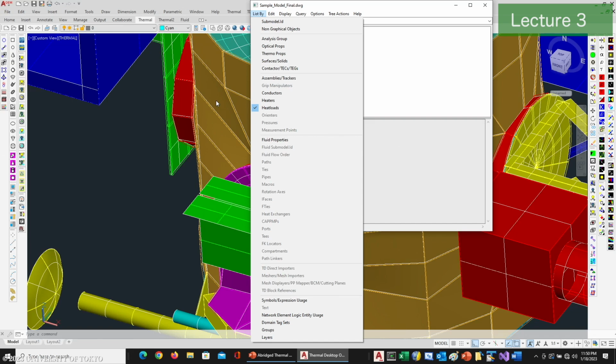So now there's no longer a need to line up my nodes with where my thermocouples are for testing. I can just put a measure there, and it will do the calculations to figure out what that temperature needs to be there. It's basically using the same algorithm that is used for the mapping of structural grid points onto thermal surfaces. Using those shape functions, it figures out the point here and knows the temperatures at the corners. So it will do the math to figure out what the temperature is at that location, same way that the contours are drawn.